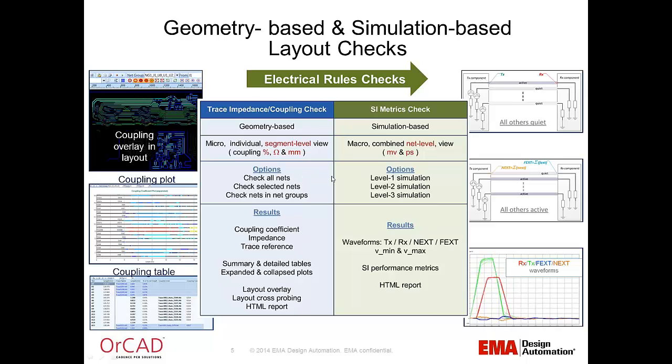You can also take it one step further in level 1 and level 2 with a time domain simulation, which is basically the same setup as what you would do with ERC. It just takes it to the next step, where you can actually create a waveform that runs down that particular trace and get waveform analysis results. This is a very simple setup. Again, there are no models required. You just define the signal itself and begin a time domain simulation that gives you the performance metrics very quickly.